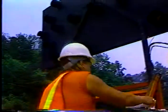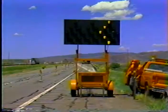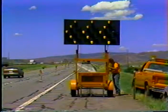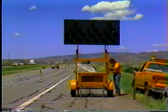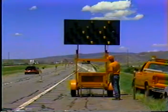Burned out bulbs need to be replaced promptly so that these important devices can provide drivers with a clear, easily understood message. Most arrow panels have automatic devices that dim the lights during hours of darkness. Make sure it works. At night, an undimmed arrow panel is bright enough to blind approaching drivers.